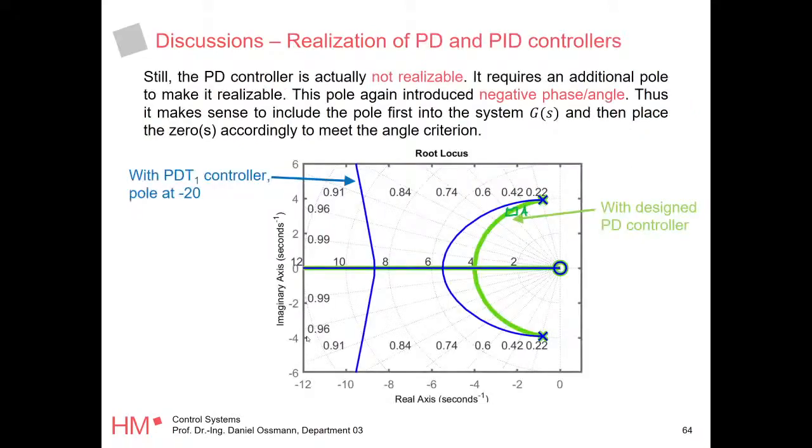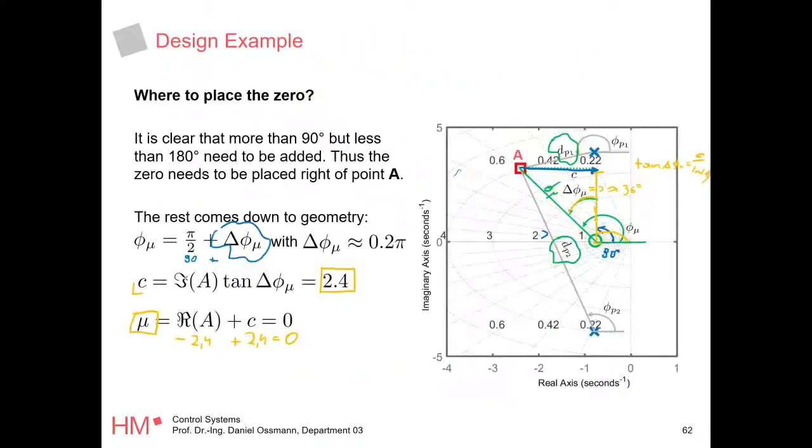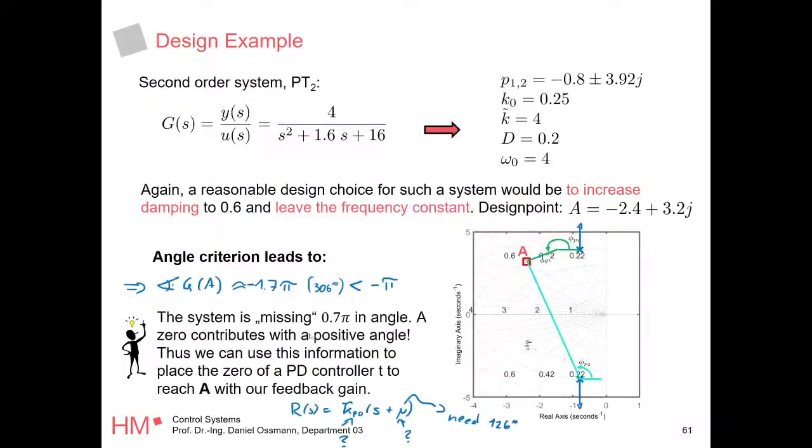In the last example, it's probably this one here, right? So let's think about it: you could add 0.3, you would add a pole. This pole would give you negative phase. Yes, I would recommend going with this minus pi, because what would happen is, you would clearly need to add a pole to make the phase more negative, right?